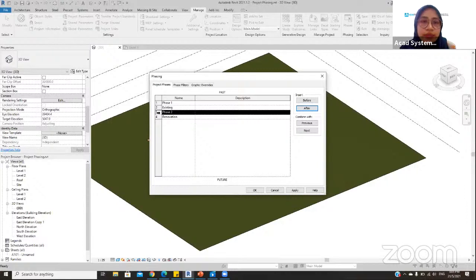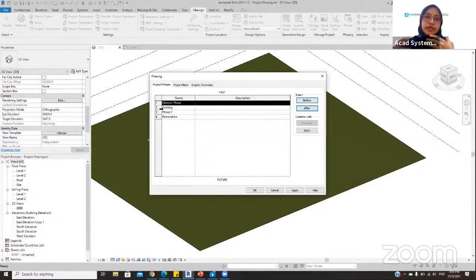All right. So what you can also do is, let's say over here, I put on the historic phase. And after I have done some of the modeling inside the historic phase, let's say I want to also combine them with the existing model over here. You can go to the Combine here and click on the next, and I will combine with the existing. Anything, drawing, anything modeling that you put under the historic phase goes into the existing, we combine together.